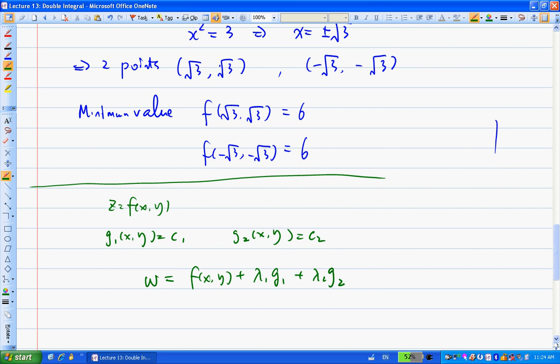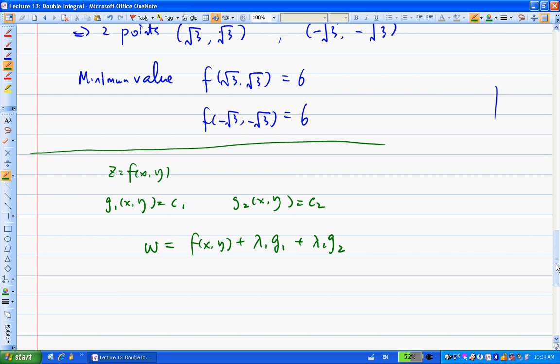This is a very useful tool in terms of optimization. In optimal control systems, this is a fundamental thing you start with. You define yourself a performance index, and you define yourself a constraint. Usually this constraint is the system. Let's say you have a mass spring damper system. The system equation may be mx double dot plus bx dot plus cx equal to 0. That's the system, right?